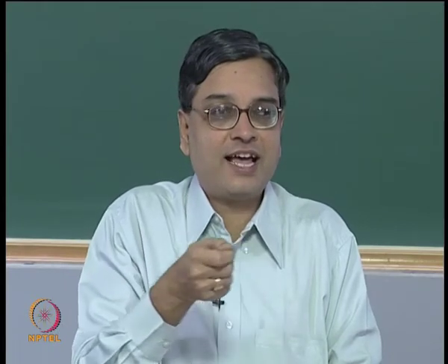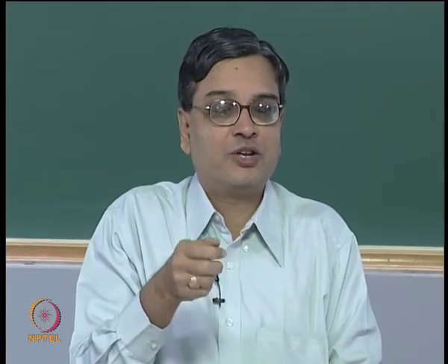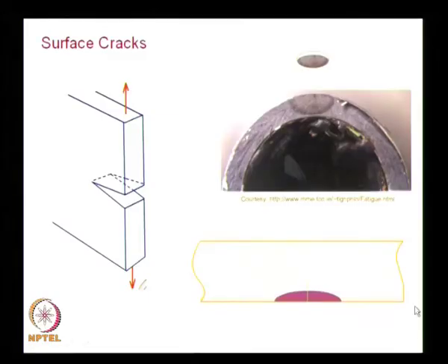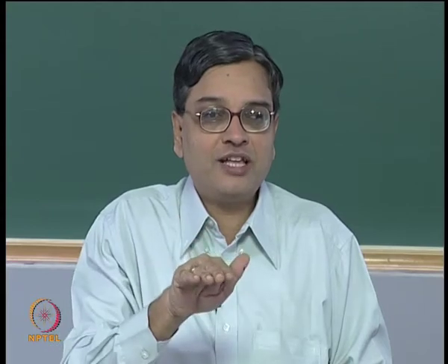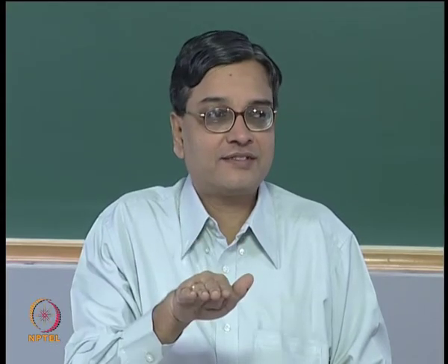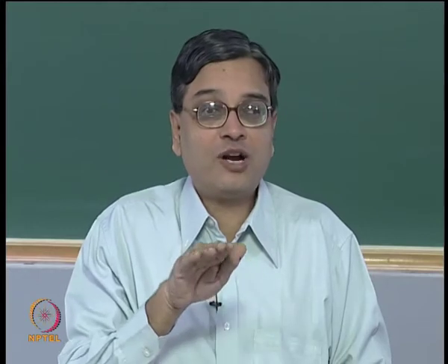So, if you have a scratch, when you are concentrating on the tip of the major axis, there is no depth on that side; it is as good as a simple scratch. In fact, the crack should not extend in that direction, otherwise even scratches will become very dangerous. When you have a scratch, because of corrosion products, the crack penetrates into the material. So, you have to look at what the crack front is.